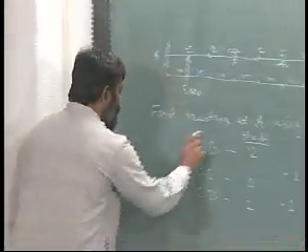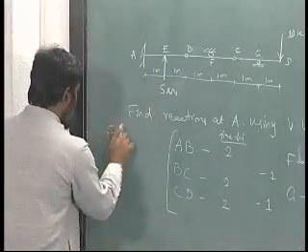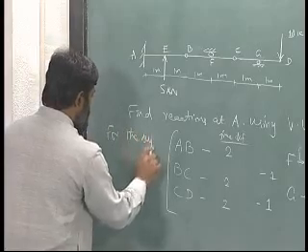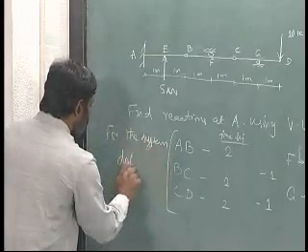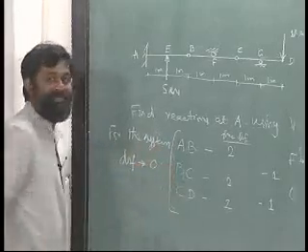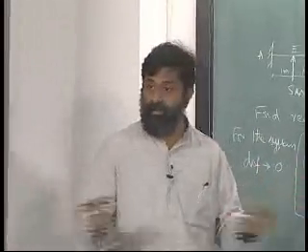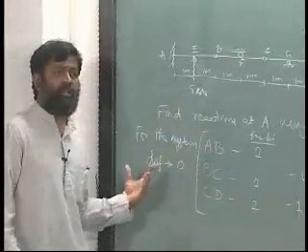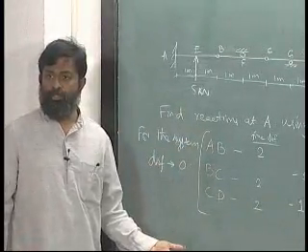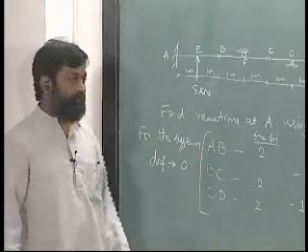Okay. So, for the system total degrees of freedom equals 0, which means it is a determinate system, alright, which means what? I can use equations of equilibrium to solve it.